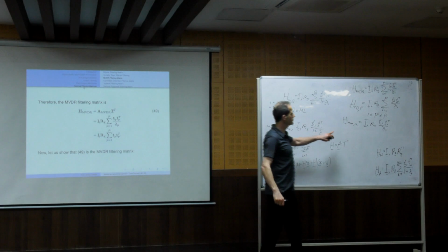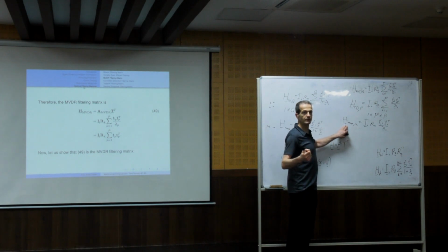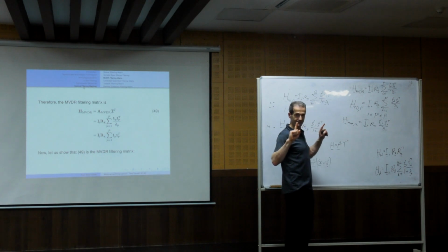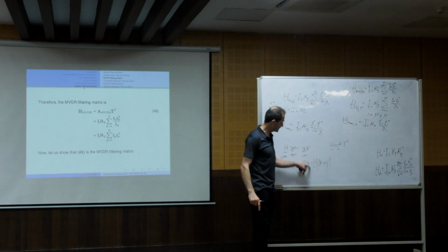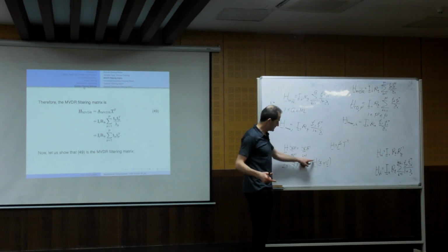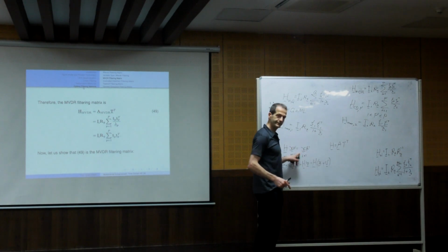Here, out of all the matrices that obtain the maximum SNR, I choose the one with the minimum distortion, minimum signal distortion, which is different. Okay? Minimum distortion is this part becomes as close as possible to X1. What is MSE? That this part is as close as possible to X1 in the mean squared error sense. It's different.